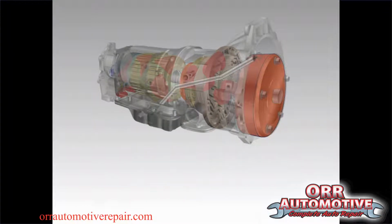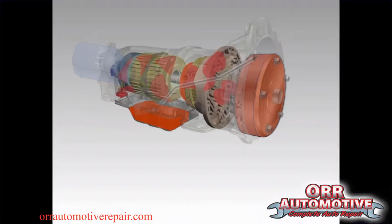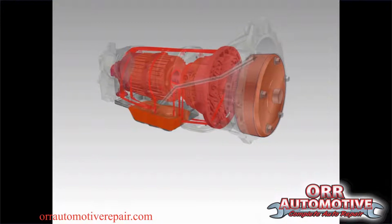New transmission fluid is added to the transmission, and as soon as it reaches the appropriate level, the vehicle is started and the fluid level is checked again. A drain and fill service replaces most, but not all of the transmission fluid, whereas a machine service replaces all of the fluid, but not the internal filter. Combining both methods ensures that all the fluid and the internal filter are replaced.